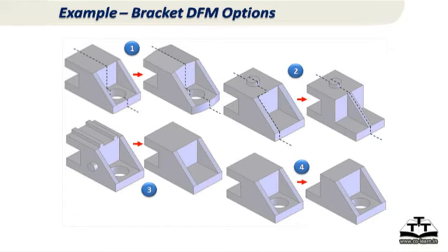The designers have put the draft. Oh, so nice. So there is no weight difference between my design part and manufactured part, because I am not adding any additional draft. Okay. Second one, you can see moving the rib to the middle, undercut is reduced, tool complexity or number of tool elements reduces. Third one, again you are simplifying the part shape, complexity reduces.